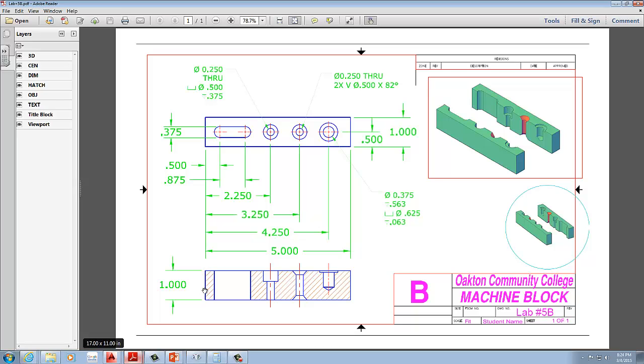And then we will also bring over the geometry for the slot and the hole geometry, and we'll use it to mark the locations for the holes, which we will take this view of and use revolves and 3D rotates to place them onto a square block that we will subtract from. So let's get started with that.